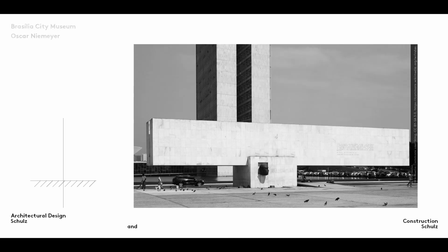With a fixed clamp bearing, one structural member is clamped in another. You can imagine this as a hand firmly gripping a hammer in order to knock a nail into a wall. The huge crossbeam of this building is clamped into place. If it were not, it would simply tip over to one side because it's supported asymmetrically. On the left, you can see the symbol for this type of bearing. It can transfer vertical forces, horizontal forces, and moments.